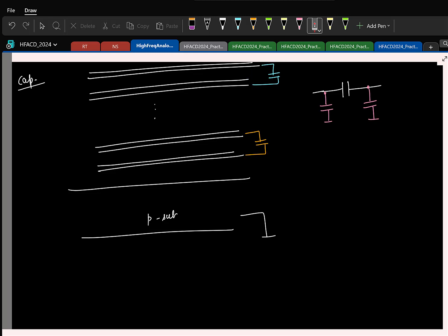Do you think forming the capacitance using the two bottom metals is better? Top one is better because the parasitic capacitance from this metal to the substrate is going to be very small. So typically that is why it's done in the top two metal layers. And in many processes, you will have two reserved metal layers in the top, just for making capacitors. Right?